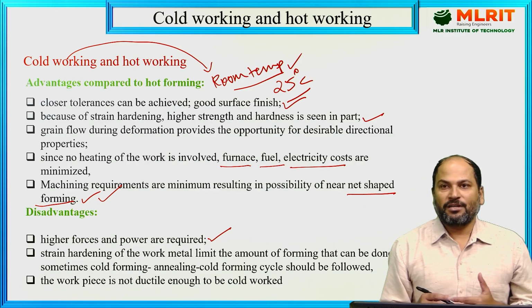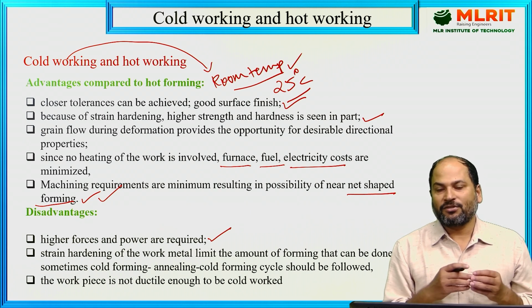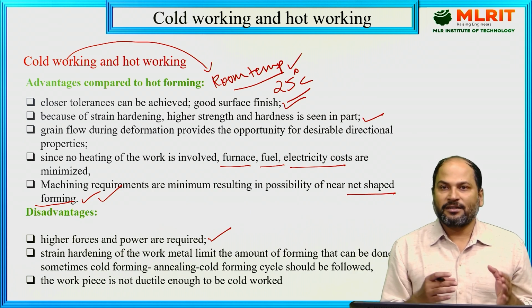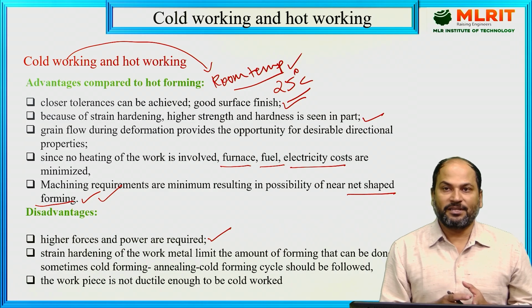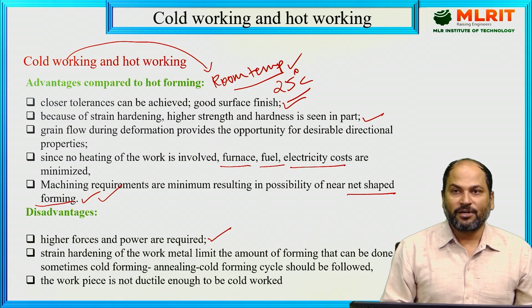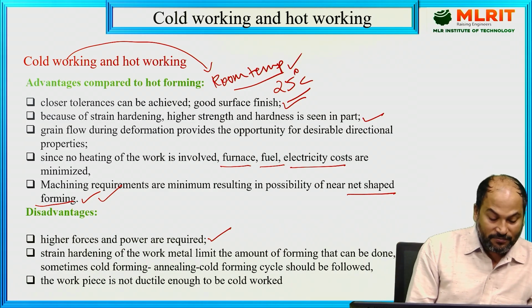So because of the deformation, there will be strain hardening. Because of strain hardening, the strength and hardness will increase. If the strength and hardness increase, then further deformation will become very difficult. So this is the disadvantage of this one.